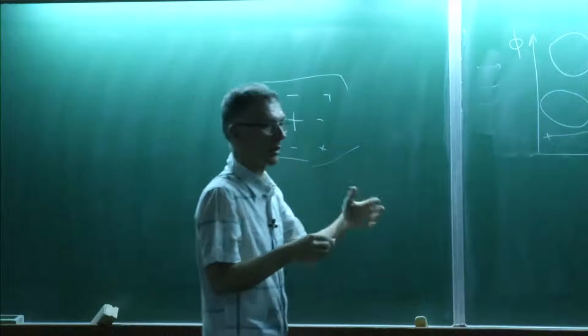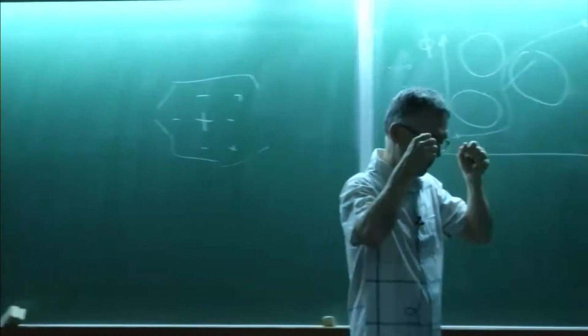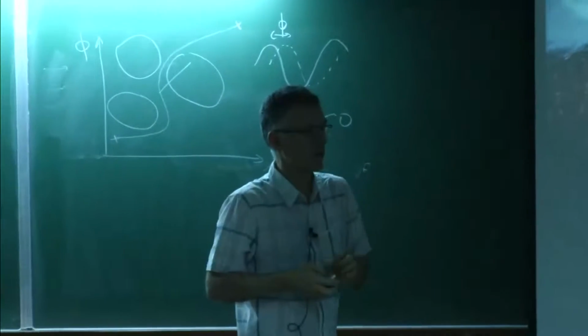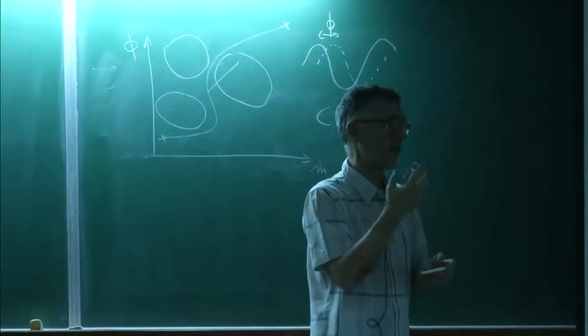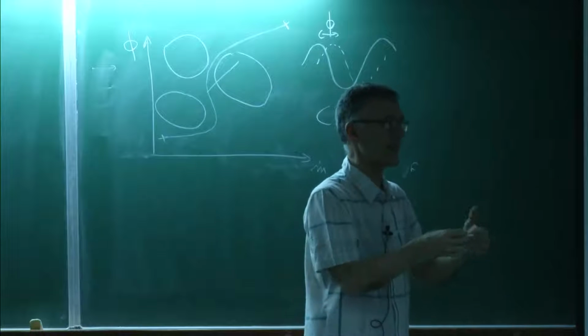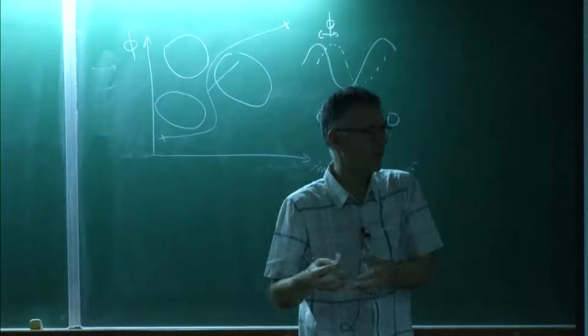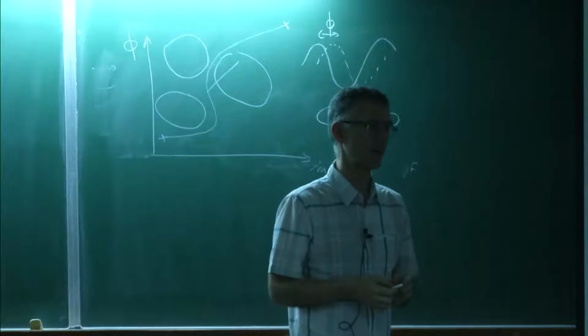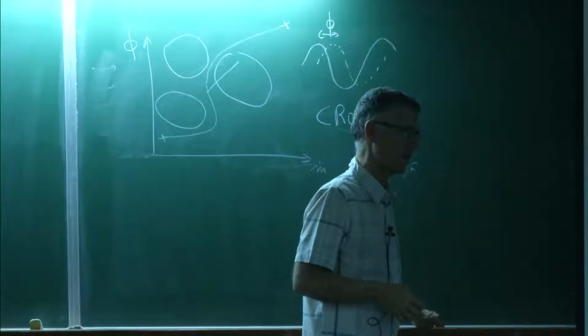In other words, coming back to the swing, there are some places of the flame pushing the swing and some places going against the swing. I will actually show examples where combustion can stop a combustion instability. If you release heat at the wrong moment, then you can stop the combustion instability. So the Rayleigh criterion, I will talk about it later. I mean, the Rayleigh criterion is a strange quantity.